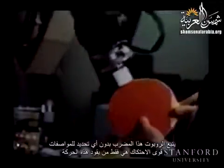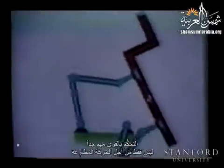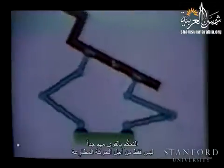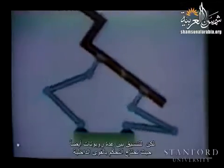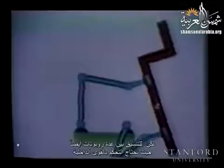These were developed in the late 80s. Here is a very nice example. We are following this racket without any specification. Just the contact forces are driving this motion. So force control is very important, not only for compliant motion, but when you do cooperation between multiple robots, it is also the same requirement. You need to be able to control internal forces, otherwise you will break the object.